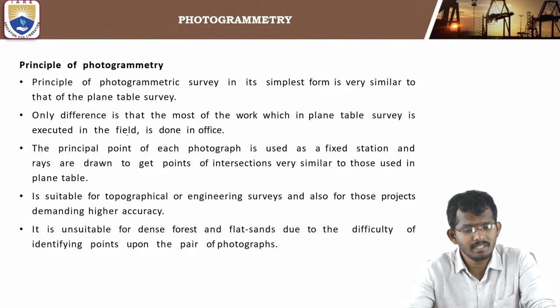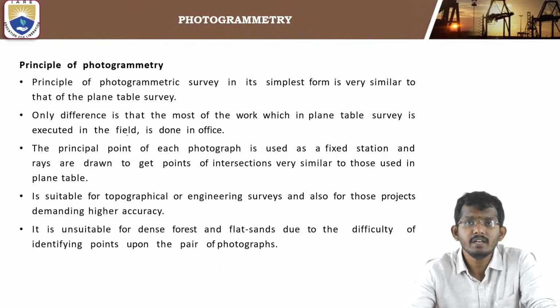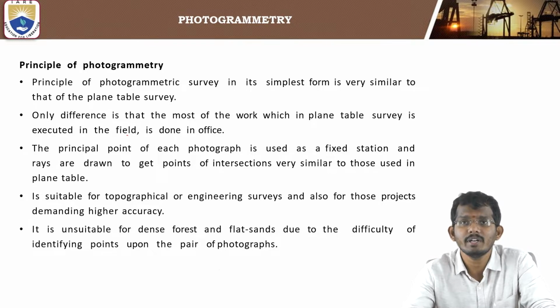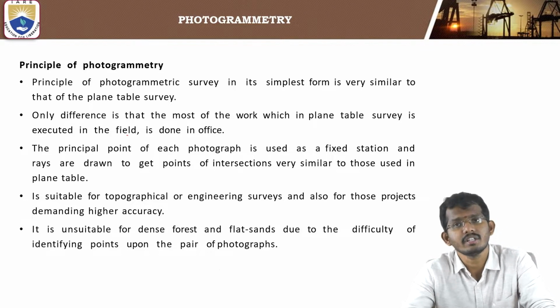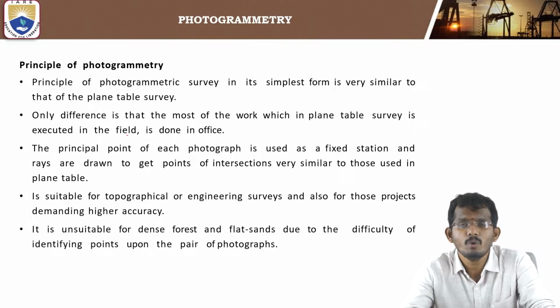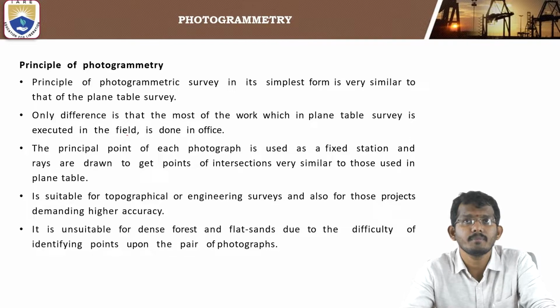Whereas in plane table, we go to the field, we work physically, we have physical contact with the instrument and ground, we measure with the measuring tape and we record on the drawing sheet. Whereas in photogrammetry, only by capturing the images, in office work we go for the analysis by visual image interpretation technique or digital image processing techniques, and we extract the information of whatever data we have captured.